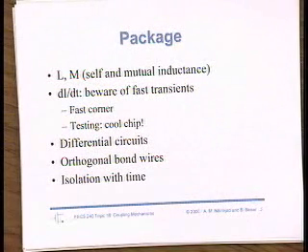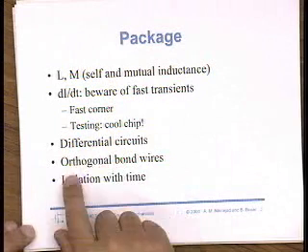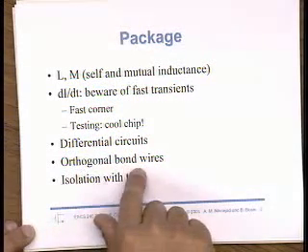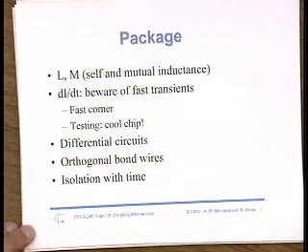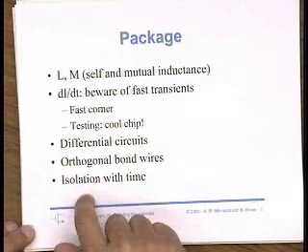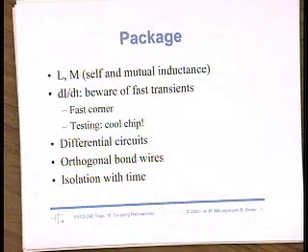or voltage noise. Don't really call it noise because it's not really noise, right? It's a deterministic waveform. But if there's lots of gate switching in a pseudo-random manner, the waveforms may in fact look somewhat random because there's so much unpredictable activity at any given time. And some ways of combating that, we talked about differential circuits, nice ways of designing your bond wires to eliminate these sources of problems, and also isolation in time. In a clock system, isolating the clock cycles where you do digital operations from analog operations, or insensitive operations from sensitive operations, if you will.